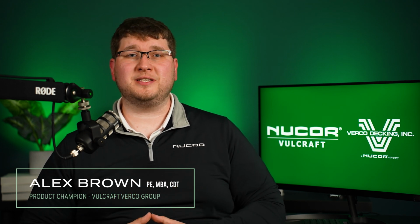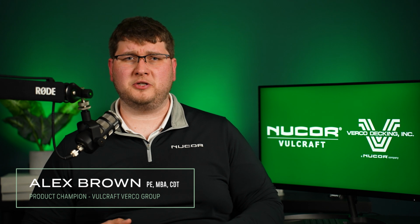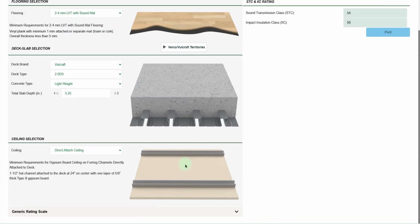This tool helps architects and engineers quickly determine the sound performance of their floor assemblies with varying flooring and ceiling treatments to calculate an expected sound transmission class and impact insulation class. Let's jump in. This tool was built to quickly verify that the selected deck and slab, probably pre-selected for structural purposes, will work with the selected flooring and ceiling options and give you the acoustic performance you're looking for.